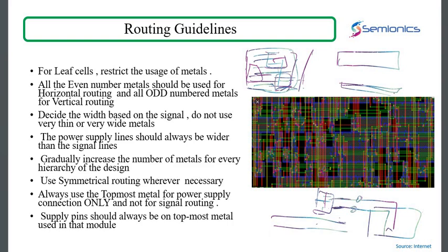So that you need to take care when you're doing a floor plan of some delay related or timing related module. You need to balance the delays. Okay, first of all, you should try and reduce the delays. The floor plan should be done in much more efficient way. Okay, if not, at least balance it. If you can reduce the delay, reduce the routing length, very good. If not, at least try to balance it.